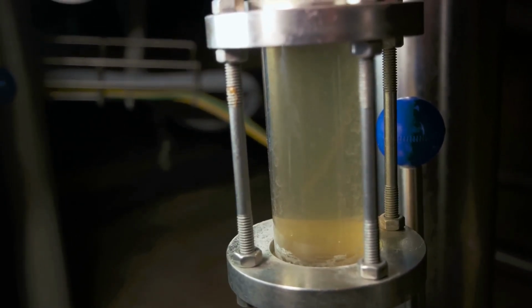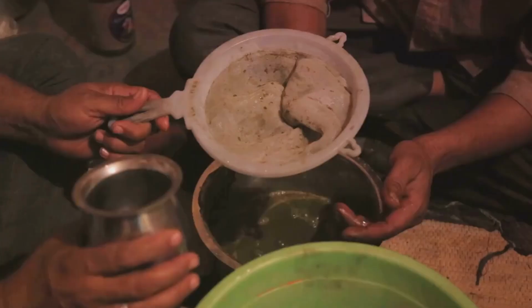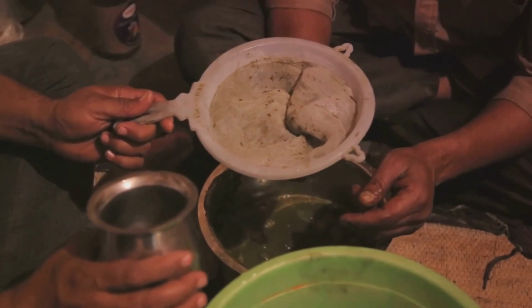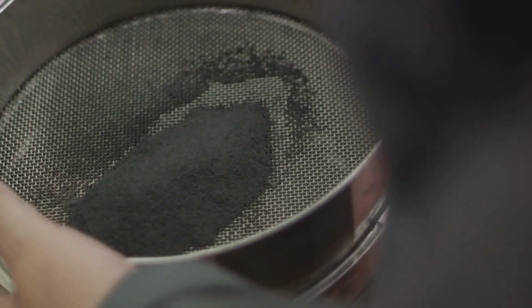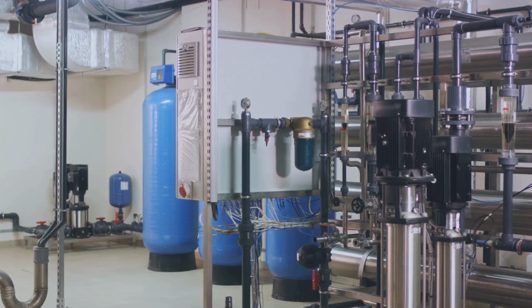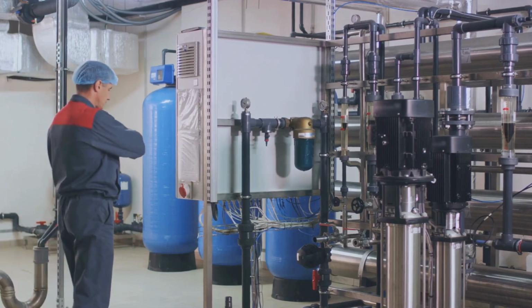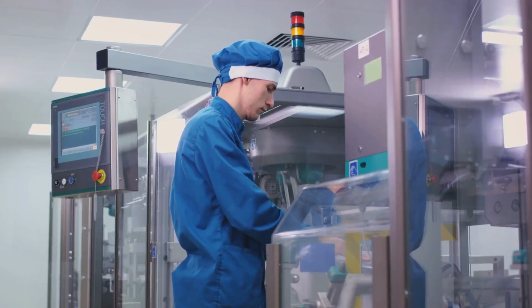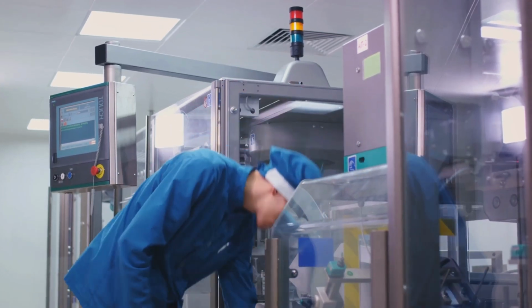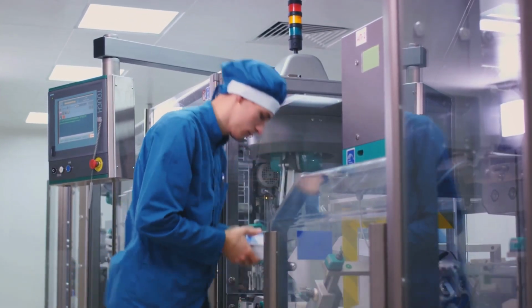The model employs the concept of a porous zone in which the volume is occupied by porous material. User-specified material porosity and directional loss coefficients define this. Fluent solves the standard fluid flow equations throughout the porous medium with a source term to account for the pressure drop and momentum change due to the porous material.